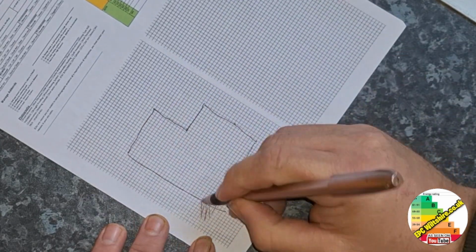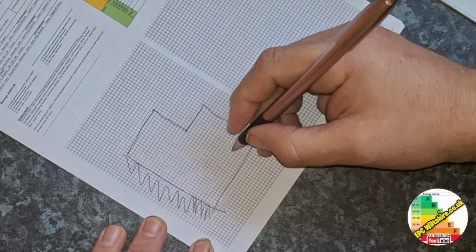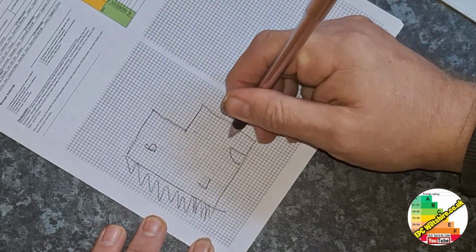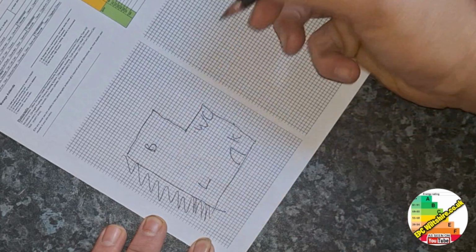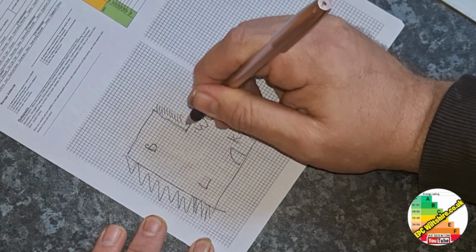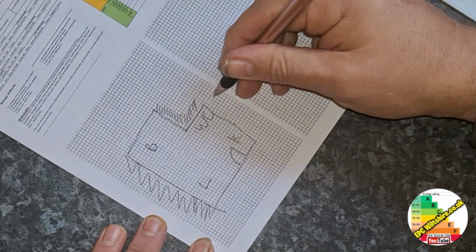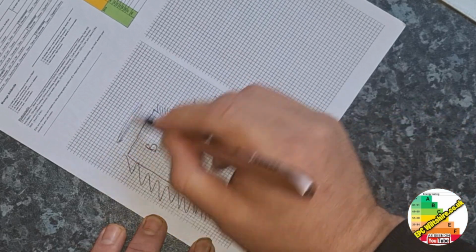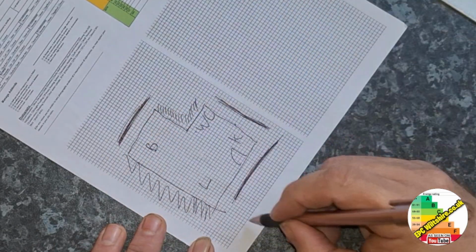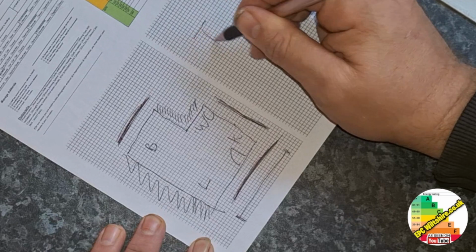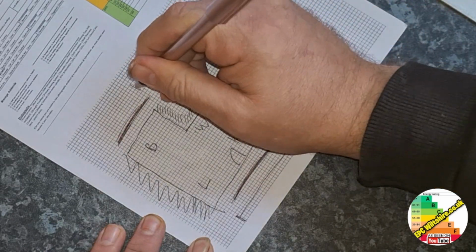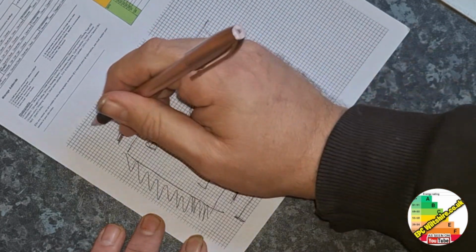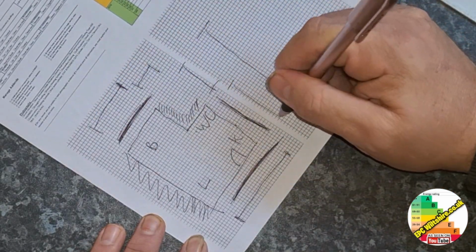and that's basically the shape of the flat. That's the party wall. The door is here. This is the lounge, this is the bedroom, and this is the kitchen and WC. So this is a party wall as well, because it's a stairwell for the flat above. And we have heat loss perimeter. So we need to know width, depth of main, minusing off the stairwell. Probably want to know that one as well, and that one as well.